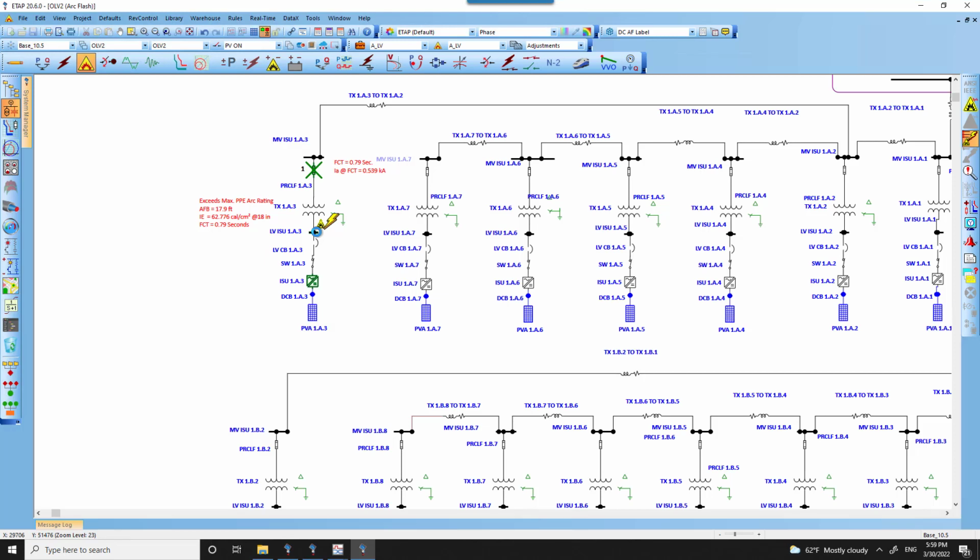We did provide some suggestions with actual mitigation techniques that would be based on working distance. In order to make sure the actual working distance is varied, as a solution for mitigating the incident energy, we used our tools in ETAP to predict and explain to the client how much the incident energy would differ based on the working distance mitigation technique.